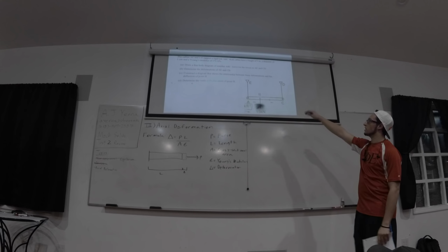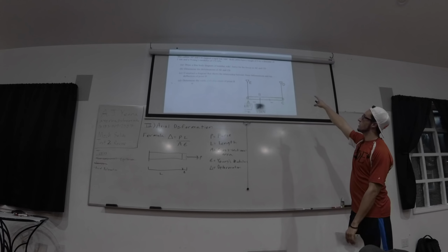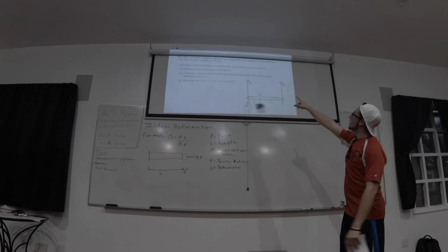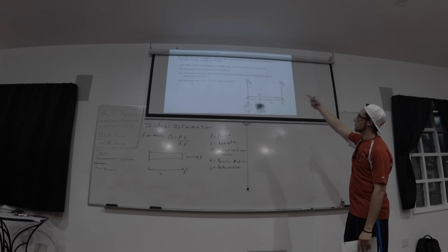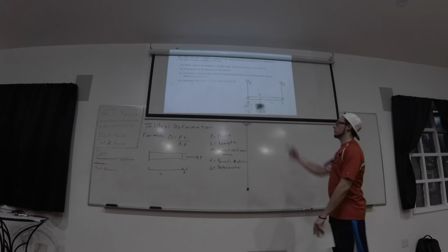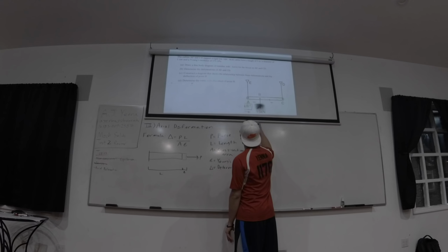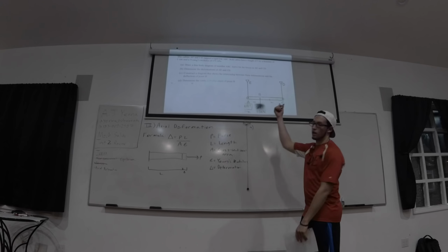You have beam AC, cables AE and CD, both of which the Young's modulus is given, like I said. Any relevant length, that's pretty much it. So step by step, we'll start to work through the problem. Part A, draw the free body diagram of ABC, and then solve for the forces.